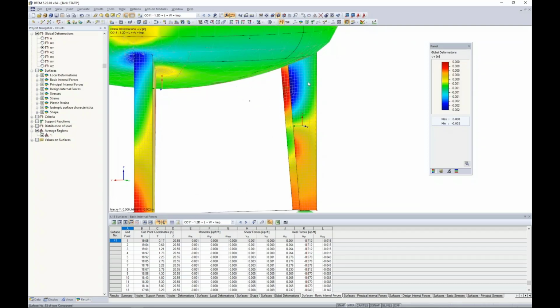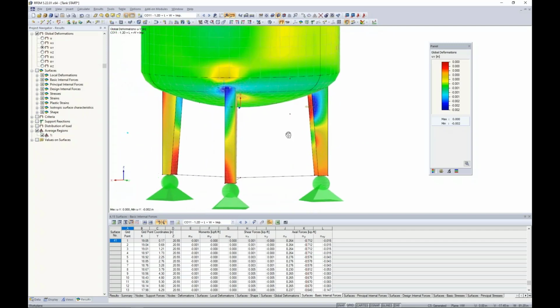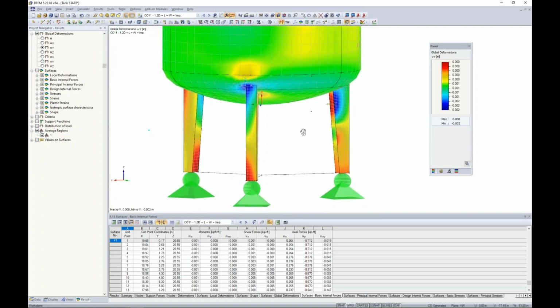We have, ever so slightly, some deflection here in the Y direction that indicates that the mesh was deformed. So possibly with a third order analysis too, we could even see more of those results available to us. But this in general is just one way that we can directly model these imperfections, because again, not everything is going to be perfect as we're modeling here, but rather there will be errors with the manufacturing or installation process.